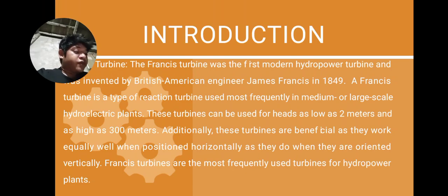The water flow enters the turbine impeller, where the hydraulic energy of the fluid is converted into mechanical energy via a shaft, which is then connected to a generator. The generator converts the mechanical energy into electrical energy, which can be used to power the equipment in the plant.